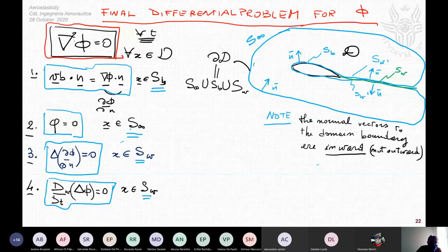In particular, in aeroelasticity the body is moving, the walls are moving walls, for the aircraft, for the wing. So we have time here, imposing the boundary condition, and we have time here. These are the sources of unsteadiness in my flow to be considered.